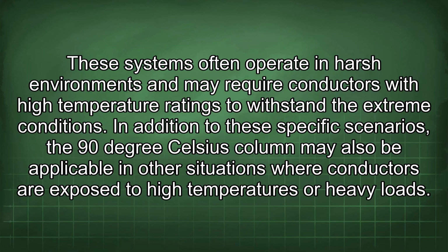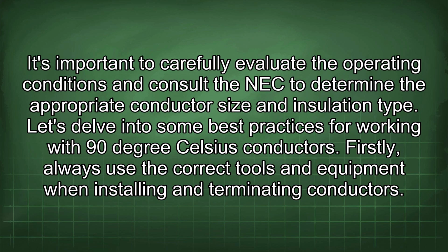In addition to these specific scenarios, the 90°C column may also be applicable in other situations where conductors are exposed to high temperatures or heavy loads. It's important to carefully evaluate the operating conditions and consult the NEC to determine the appropriate conductor size and insulation type. Let's delve into some best practices for working with 90°C conductors.